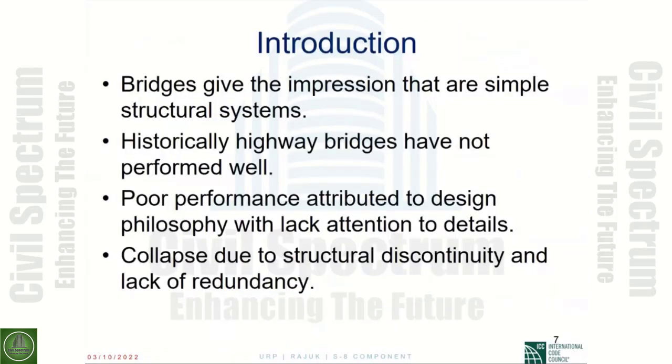The first thing, when you look at a bridge, is that it gives you the impression of a simple structure. That's actually not the case. These are really complicated structures because of the geometrical shape of the bridge. Most of the mass is in the deck, and based on the heights of the columns and the geometrical shape of the bridge, whether it is skew or curved, it gives a very complex behavior.